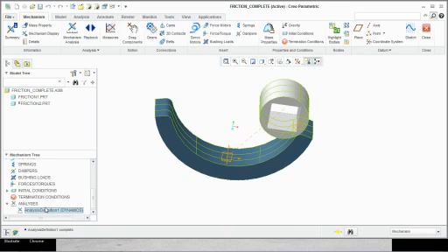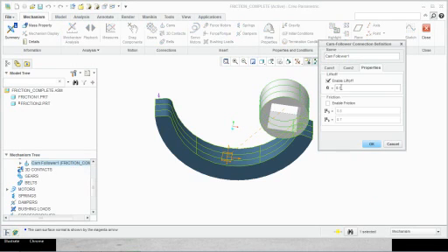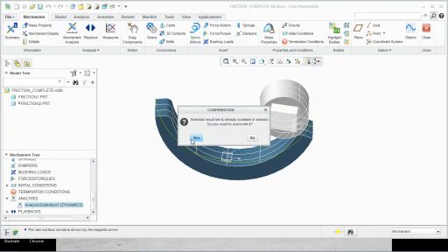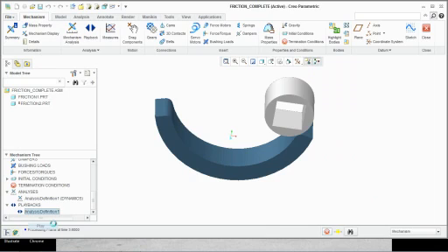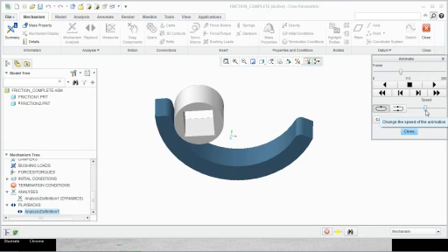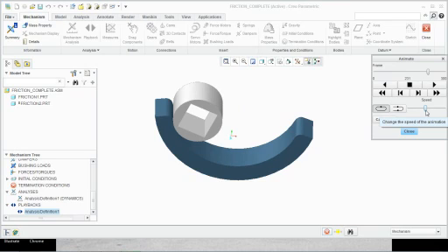I go ahead and enable the liftoff, and I start off with the coefficient of restitution, and I enable friction. You can see how, when you enable the liftoff, the connection need not be constant. You can see it's sliding too. So I'm going to run a playback on this one real quick for you to see. You can see it rolls, and then right now it's going to slide a little bit. See that? That's slippage. So if you don't enable liftoff, that's not going to happen.